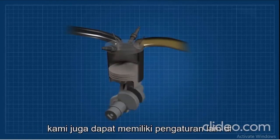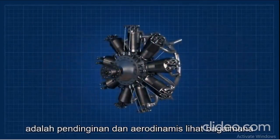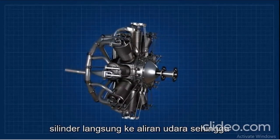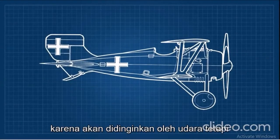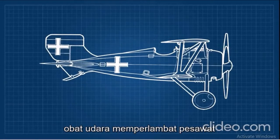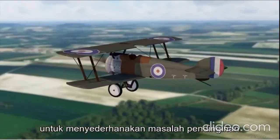In cars, you'll normally see cylinders arranged in line or in V, but in airplanes we can also have other arrangements including opposed and radial. The main difference with these arrangements is the cooling and aerodynamics. See how a radial engine is exposing all the cylinders directly to the airflow. Thus, it doesn't need an extra coolant system since it will be cooled by the air. But this arrangement will produce a lot of air drag, slowing the plane down during its flight. Many early airplanes used this kind of engine to simplify the cooling problem.